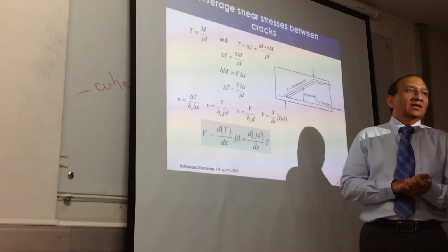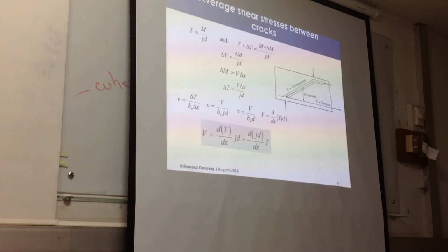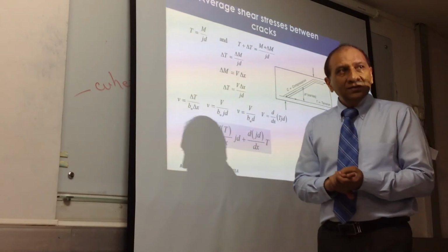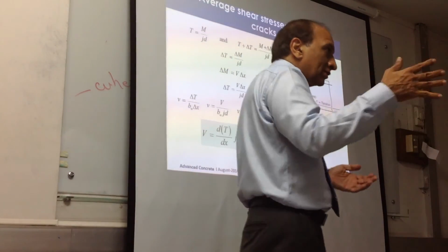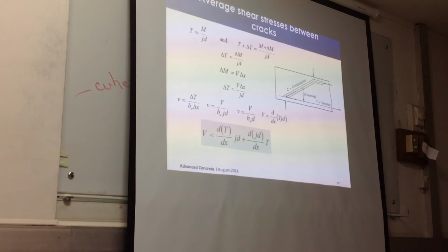The effectiveness will be less in the horizontal direction than the vertical direction because of the interaction of the other stresses that are present there. Why? If you provide horizontal reinforcement, that reinforcement will be mostly taking the tension coming from bending. So its shear effectiveness is less. But if you provide vertical reinforcement, bending has nothing to do with it. So all of that is available for shear. So that's why it's more efficient to provide reinforcement along the shear, perpendicular to the shear. If there was pure shear, no bending, either direction would be fine, right?